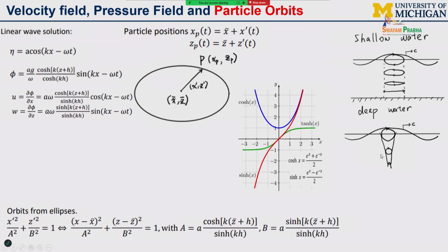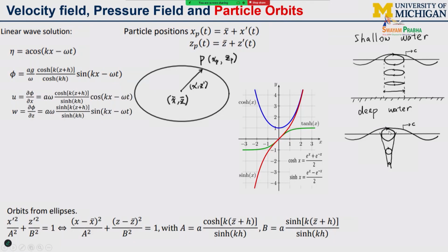Okay, when we say 5%, 23% means, okay, this particle motion, at the surface, let us say the circle area, this amplitude is 1. At quarter wavelength, this amplitude decreases to 0.2523, and at half wavelength, this amplitude decreases to 0.05, right? This says the amplitude will quickly decrease.